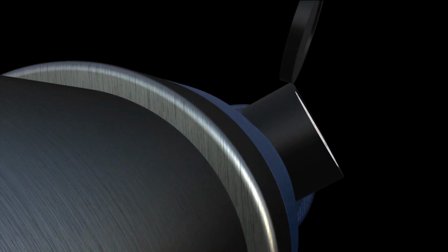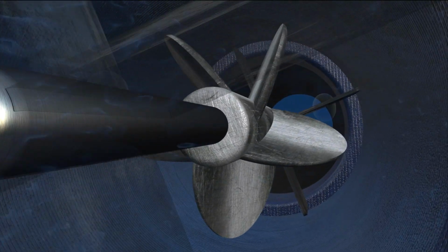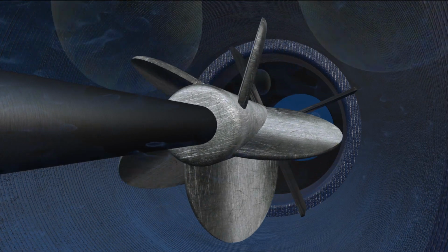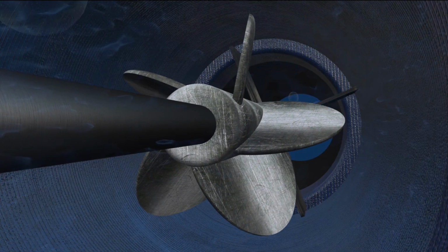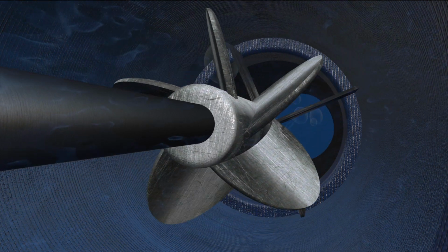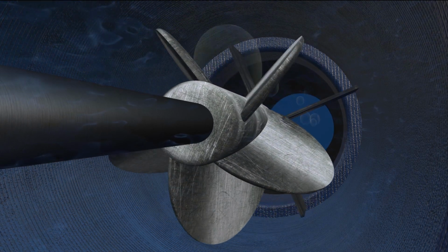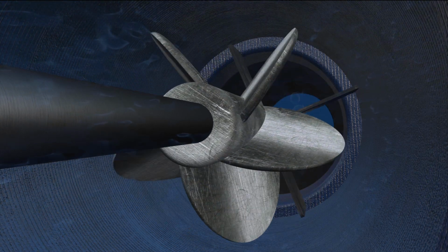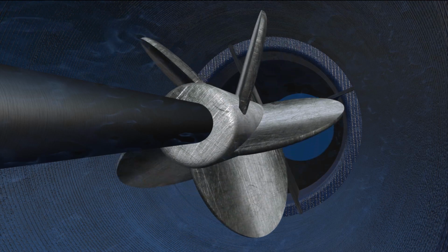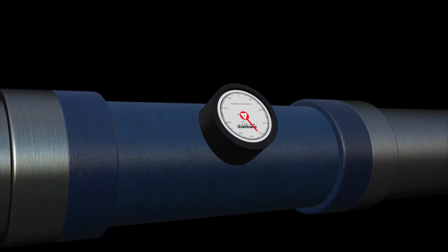Turbine meters have rotors or propellers that are turned by the flow of water through the meter. The rotational speed of the rotors or propellers is proportional to the velocity of the water and is used to calculate flow. The turbine meter is best suited for measuring flow in a distribution system with continuously high flows. The propeller meter may be installed within a section of pipe or it may be saddle mounted.